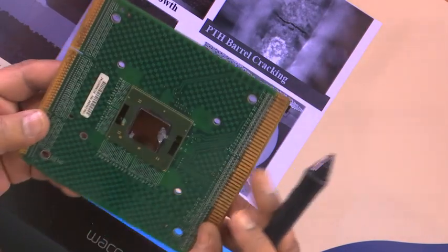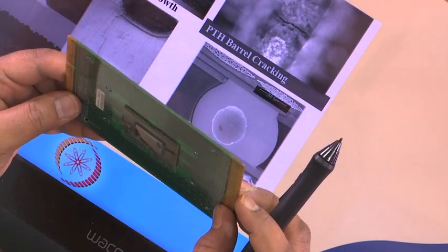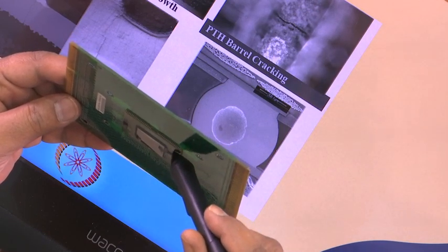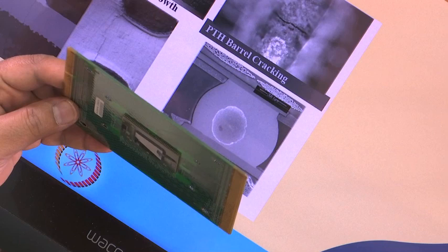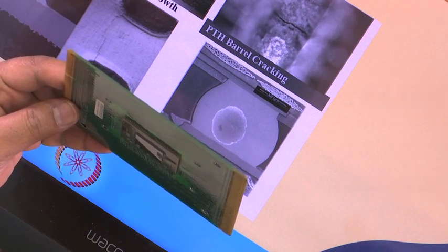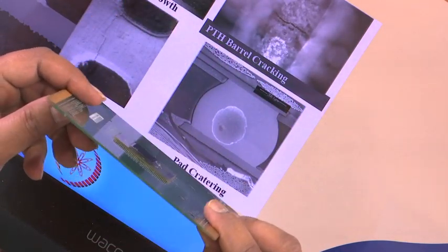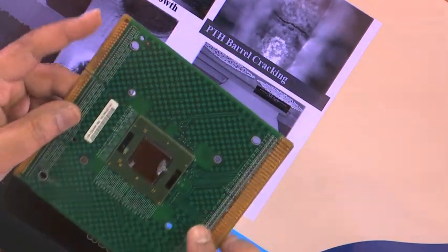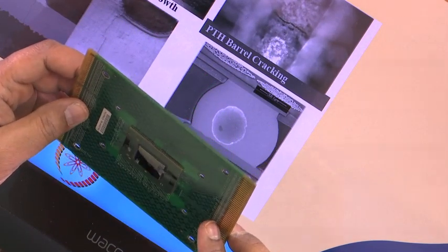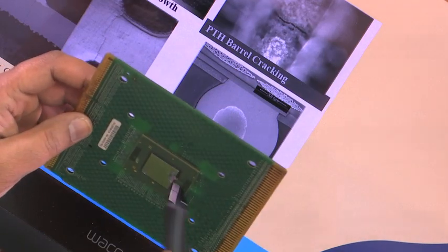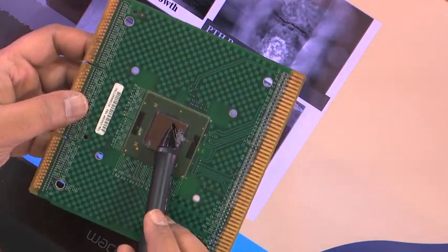Now, if you look carefully from the side, probably you can see the outer, if you look along the edge, you can see the series of solder balls, right, at least the last row of the array. The other end also you should be able to see, but again this end was more clear, right. However, I do not see that outer joint over here.